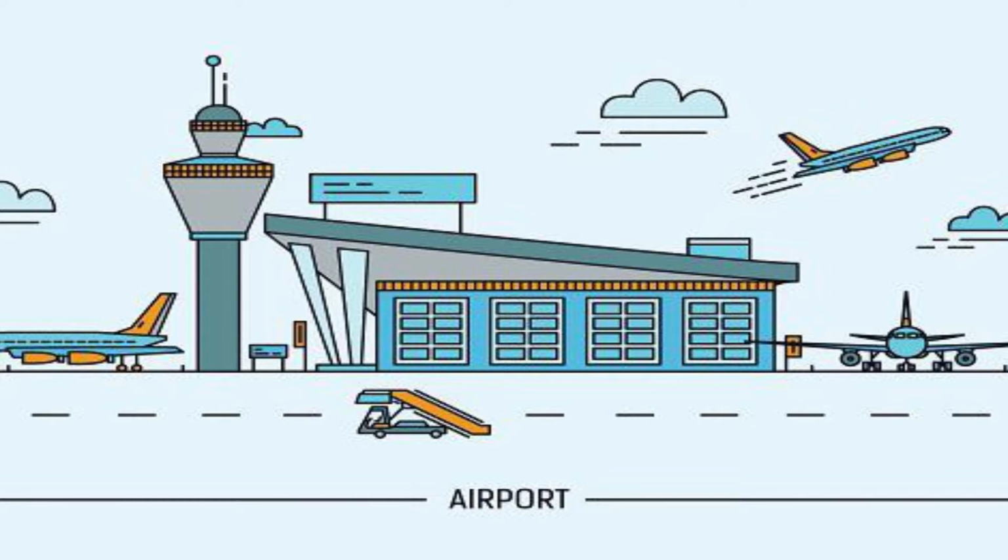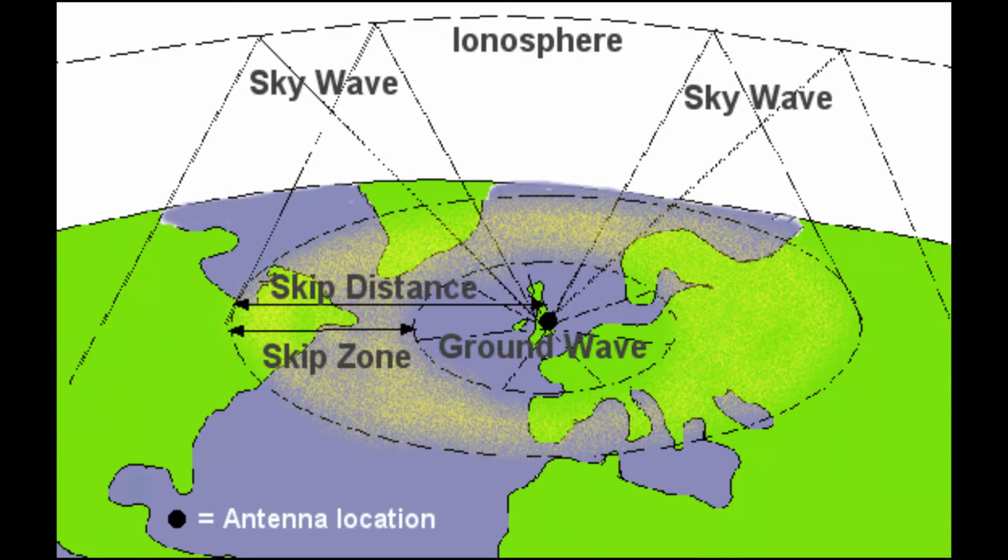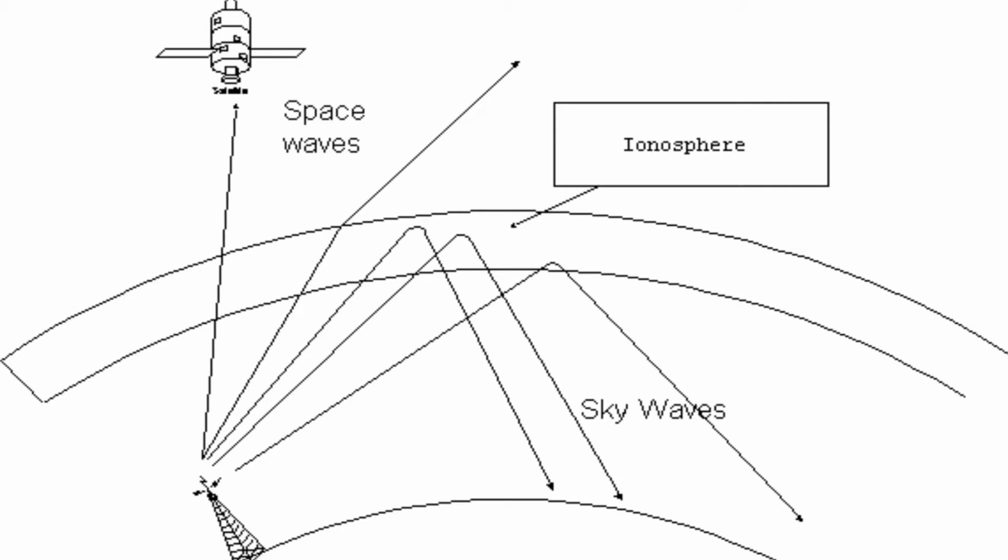High-frequency radio waves travel in a straight line and do not curve to follow the Earth's surface. This would limit transmission from the broadcast antenna to the receiving antenna to the line of sight. The frequency range is between 2 and 25 MHz. These kinds of radio waves are also known as skywaves. Above high-frequency transmission, radio waves are known as space waves. They are only capable of line-of-sight transmission.